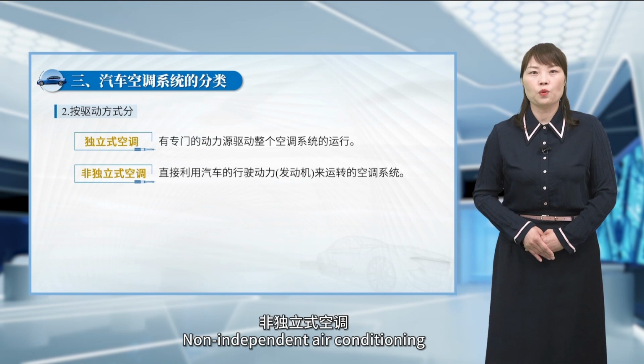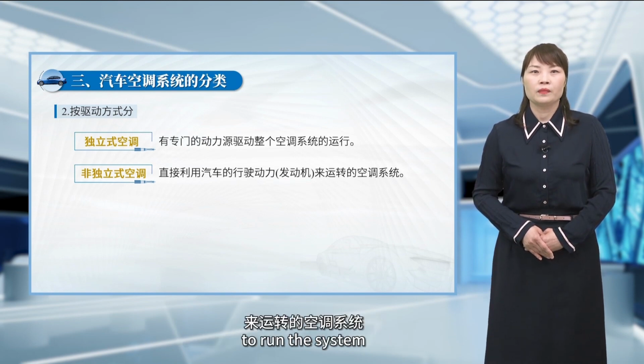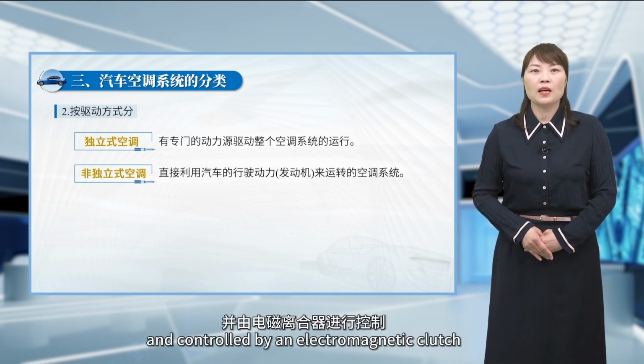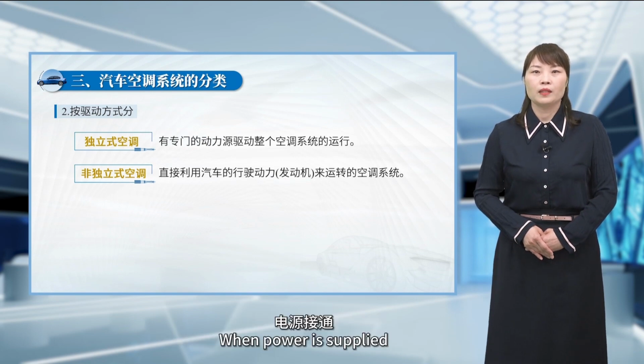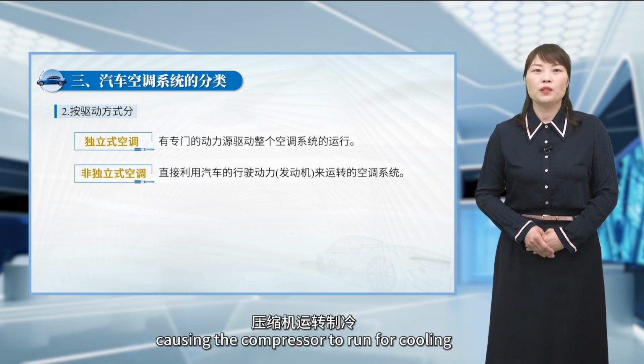Non-independent air conditioning directly utilizes the vehicle's engine to run the system. The compressor is operated by the engine and controlled by an electromagnetic clutch. When power is supplied, the electromagnetic clutch engages, causing the compressor to run for cooling.